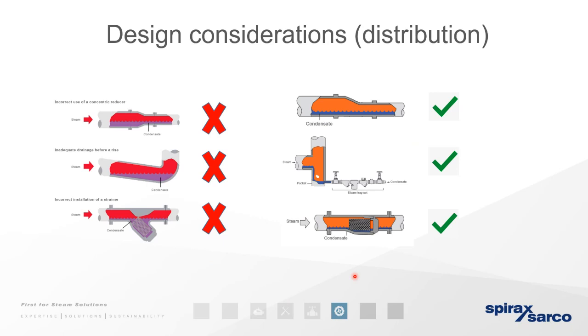And again, coming back to strainers: on a steam system, we want to install a steam strainer on its side so that we have less water buildup on the strainer, as opposed to liquid systems where the strainer is installed vertically, and therefore ensuring a pocket of water that will be collected within the strainer.